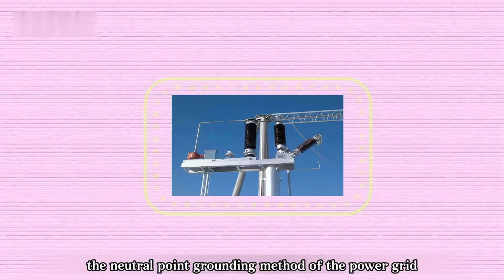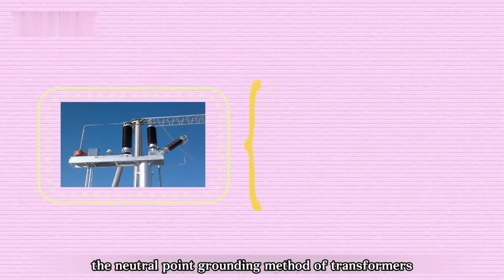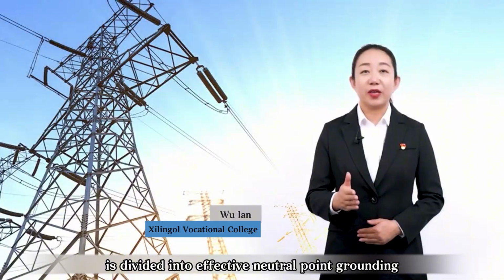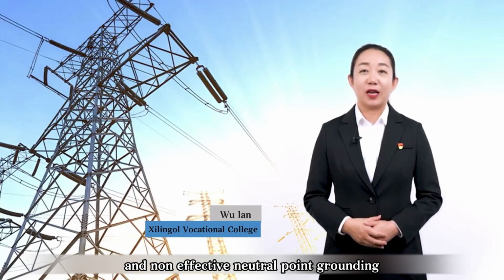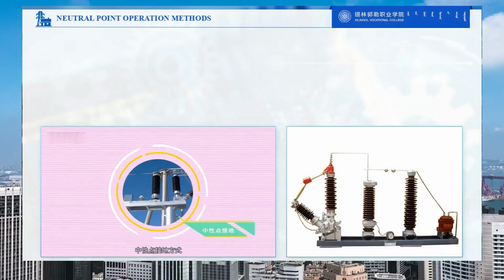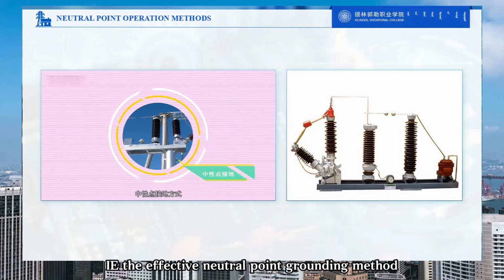Generally speaking, the neutral point grounding method of the power grid, that is, the neutral point grounding method of transformers at various voltage levels in substations, is divided into effective neutral point grounding and non-effective neutral point grounding. Power grids of 110 kV and above in China generally adopt the large current grounding method, i.e. the effective neutral point grounding method.